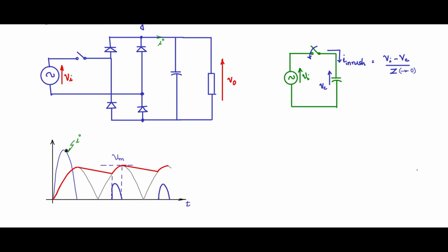Now this is a benign case where the switch turn on is synchronized with the 0 crossing of the input, which will not happen in most cases. It will not happen in a practical situation. When you turn on, it may so happen that the input is at its peak, the worst case condition.